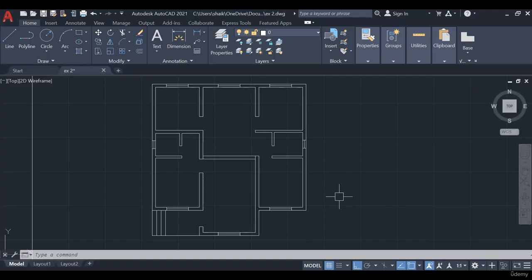After that the wall will come. So that whatever load comes, it will transfer evenly. If your wall is bigger and your plinth is smaller, then what happens? It will not easily transfer the load. There is a chance of imbalance of the loads. So that's why the plinth is kept a little larger than the walls. So that projection we need to show here.